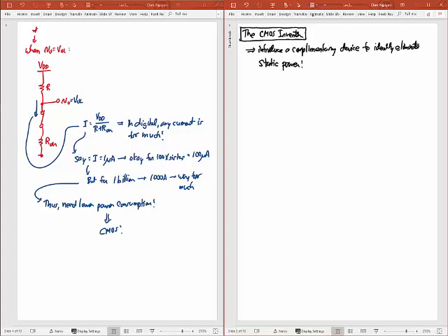Okay, so how does this look now? This looks like the following. If I have VDD here, I'm going to go into a PMOS device and stack that on top of an NMOS device, which will go to ground. Both gates I will tie together to the same input.